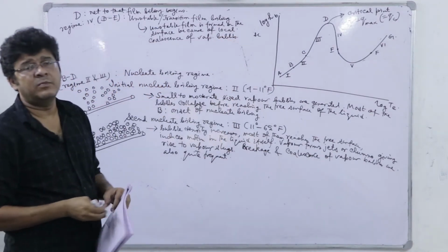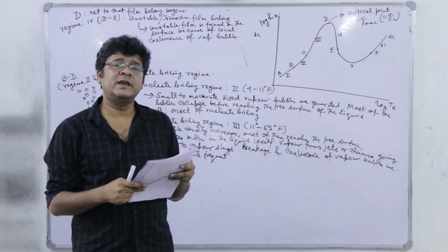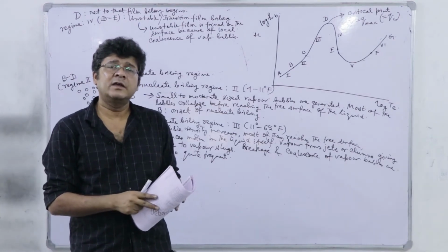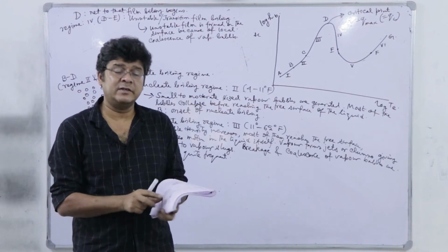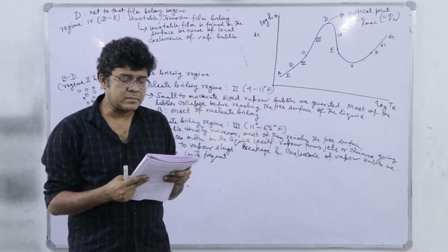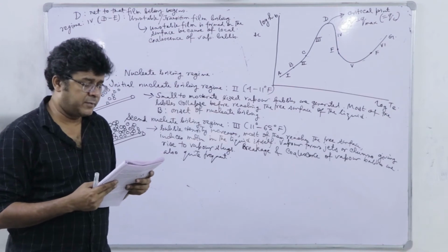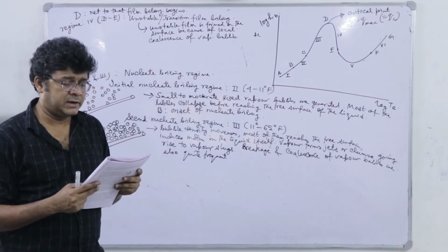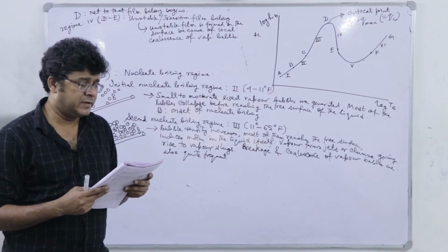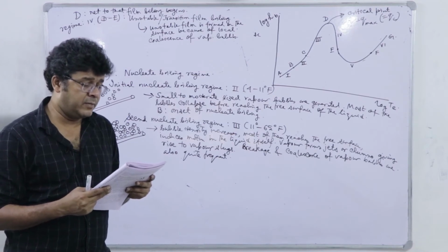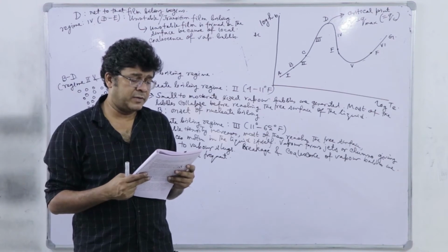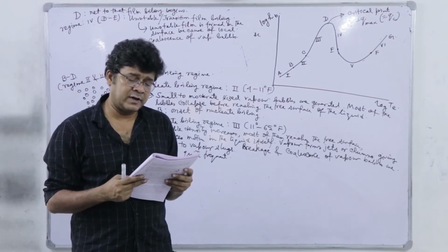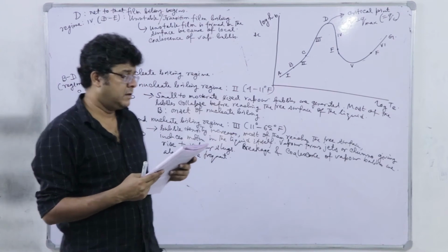However, that film is actually unstable. It may appear at one moment and it may disappear in the next moment. So, the formation of the vapor film on the surface is not complete in this region and the film is discontinuous. The film may even disappear momentarily and then reappear. This regime represents partial nucleate boiling or transition boiling, right.